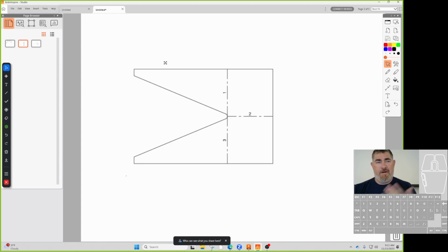Yeah, so they know how big to blank it out, right? And they can double check it a little bit. So yeah, I'd probably do the ordinate dimensioning going that way. And maybe in here I might start with my 0 here and go either of those ways. Or I can just do a regular dimension.